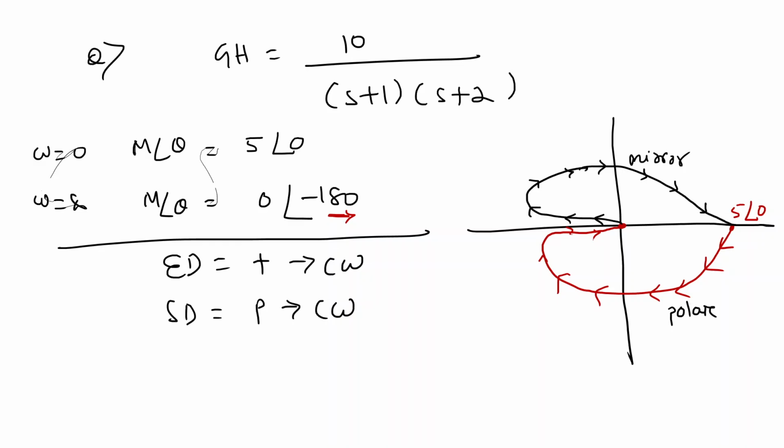In the Nyquist plot, if you go through any books or such lectures, you can understand that to find the stability, the number of right hand side poles is equal to the number of clockwise encirclements about the -1 plus j0 point.